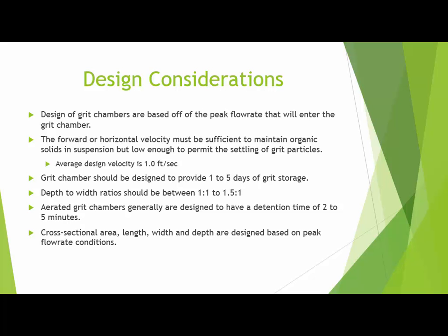Depth to width ratio should be between the 1-to-1 range and the 1.5 to 1 range. Aerated grit chambers generally are designed for a detention time of 2 to 5 minutes, and cross-sectional area, length, width, and depth are all designed based upon the peak flow rate conditions.